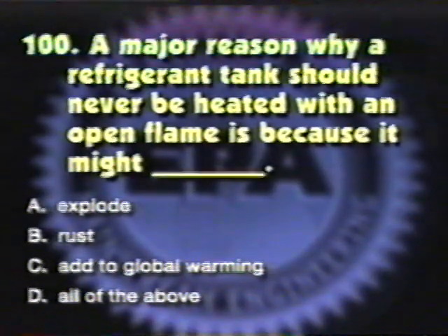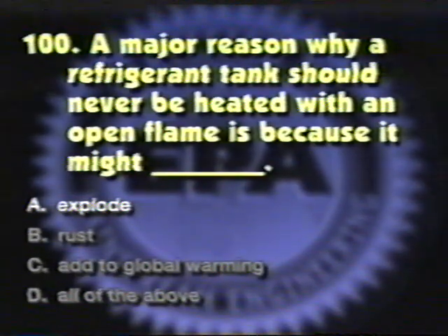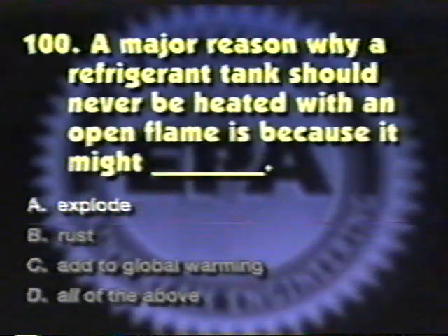The correct answer is A. The most important reason never to heat a refrigerant storage or recovery tank with an open flame is that the tank may explode and seriously injure people in the vicinity.